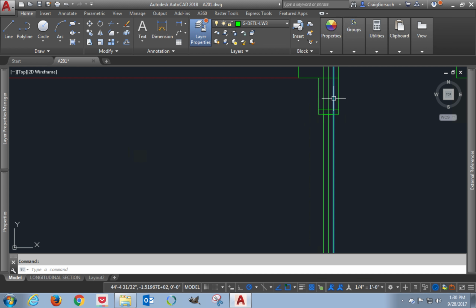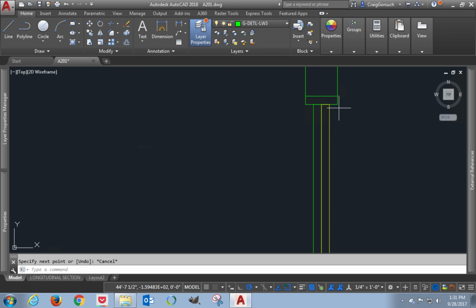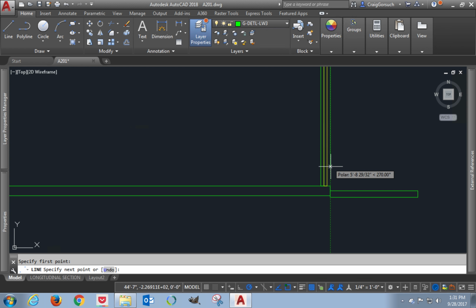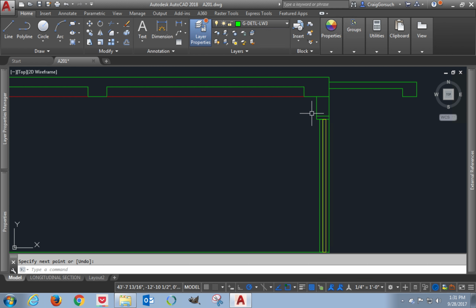Okay, so I've created 2 rectangles, and they just overlap these lines. AutoCAD is filled with times where you're going to draw things that help you draw something else, and then you delete those first things that you drew. So I'm going to highlight that line, click on it, and I'm going to set it to layer 2. And now I'm going to draw 2 more lines from there down to this end, and another one.